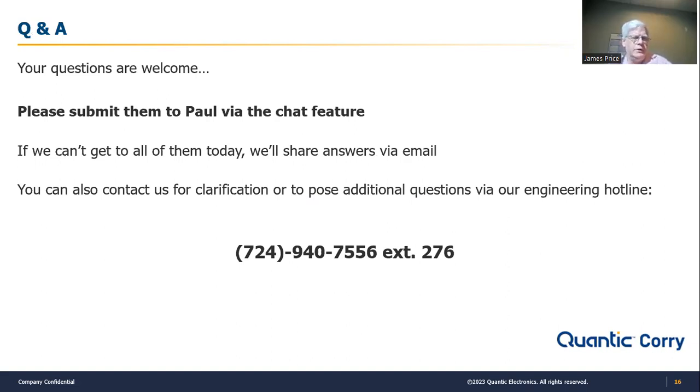But there are other kinds of filters that are tunable. One big one is a YIG filter, yttrium iron garnet. You use a little YIG sphere as a tuning element. And it's a tuning element just like the ones I showed you, and they're coupled together just like I showed you. But they operate on a completely different principle. You can tune those over a multi-octave bandwidth. They're a really nice way to go if that's the kind of thing that you need. And they go pretty high in frequency as well. 18 gigahertz isn't out of the question for a YIG filter.